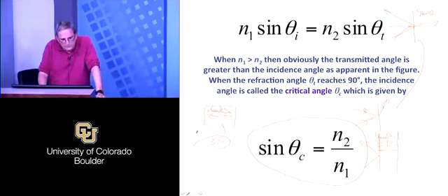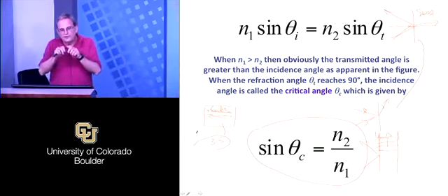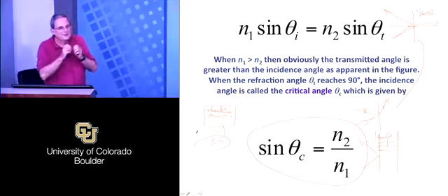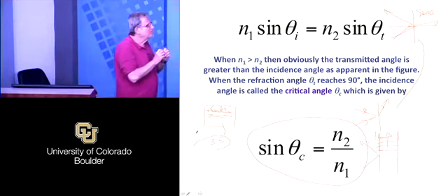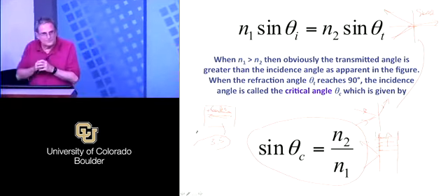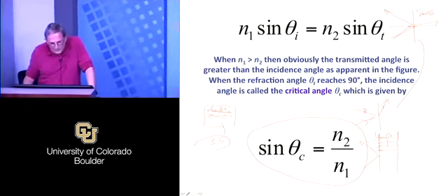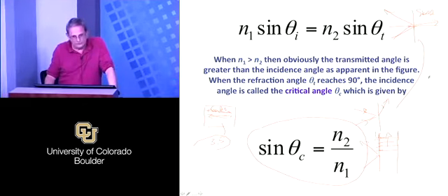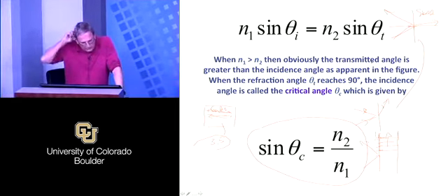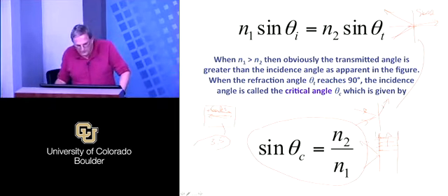Cleaving silicon is a lot easier than cleaving gallium arsenide or indium phosphide. If you try to cleave indium phosphide, it kind of breaks like a clot of dirt or something. It's nasty to get the cleavage plane right. I'm glad I don't do that for a living. It's very hard to do. But at any rate, gallium arsenide isn't so bad. Silicon is very easy to cleave, but of course you can't get inversion because it's a direct gap.